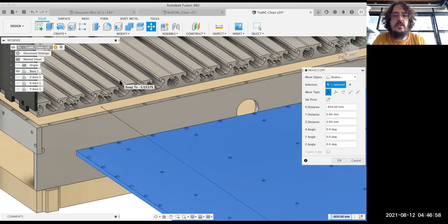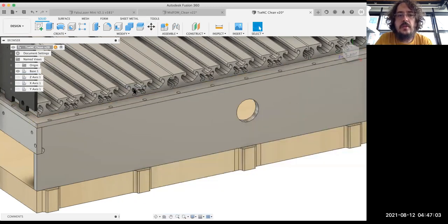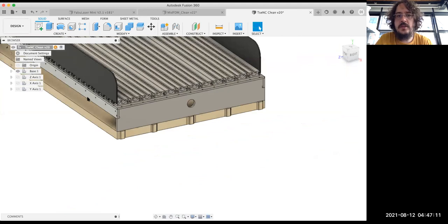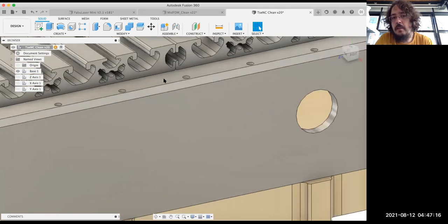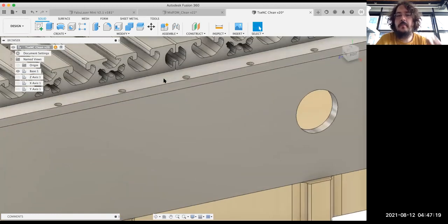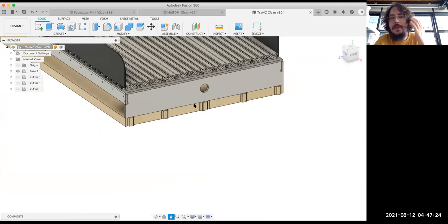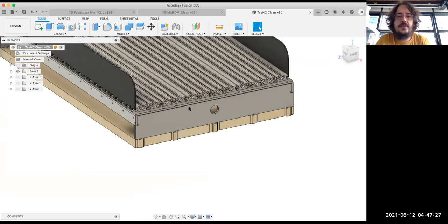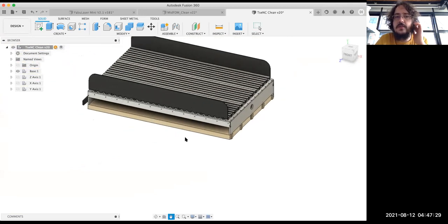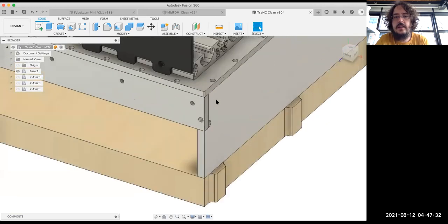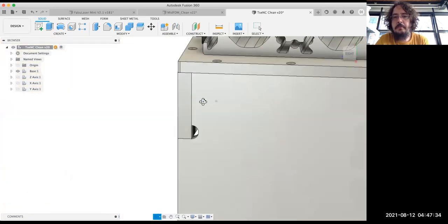All right. So this was, I think, a mistake, because I could have used these aluminum profiles directly without this plate underneath it, just by using some rods or profiles underneath it to hold it, without the need to mill and then tap by hand this big aluminum plate under it. There is a CNC in this Fab Lab that uses this second system that I'm telling you, which is much bigger and much stronger than this. So this was an extra piece that I could have saved. So the base is a very simple system. It has, again, these kinds of joints here with a tapping.